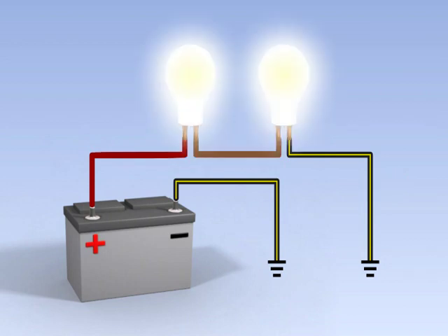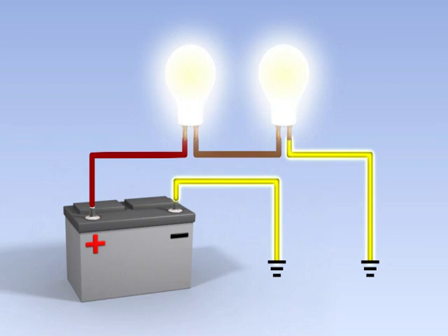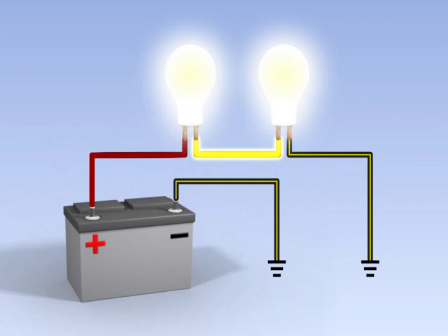It's also essential to understand that circuits have both a negative and ground side. The negative side of a circuit exists between two components and eventually leads to ground, or a common. The ground side of a circuit goes directly to ground. One special note: the color coding of the ground wires will be the same for all grounds, while the color coding on negative side wires varies. This difference is important to the troubleshooting process, as some diagnostic tests are done on the negative side of a